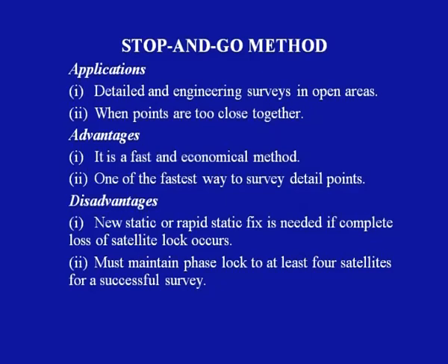The advantage of this particular method is that it is fast and economical, and one of the fastest ways to survey detailed points. However, it has some disadvantages: a new static or rapid static fix is needed if a complete loss of satellite lock occurs. It must also maintain phase lock to at least 4 satellites for a successful survey to be performed.